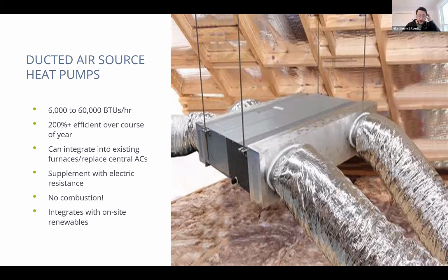There are thermostats from each of the mini split manufacturers that, instead of doing an algorithm inside of the unit, would read the temperature at the wall. And based off of the temperature at the wall, that would be informing how hard that heat pump needs to be working to get that set point satisfied.